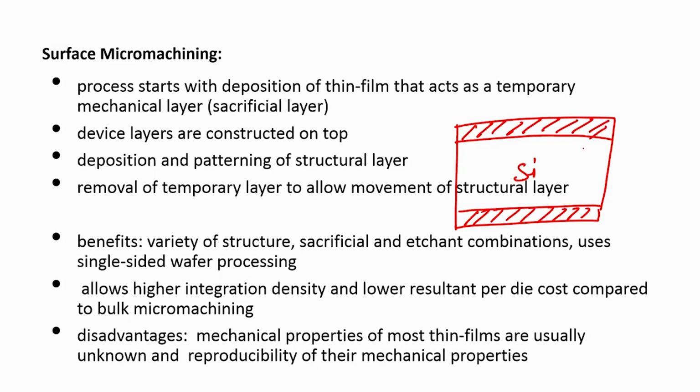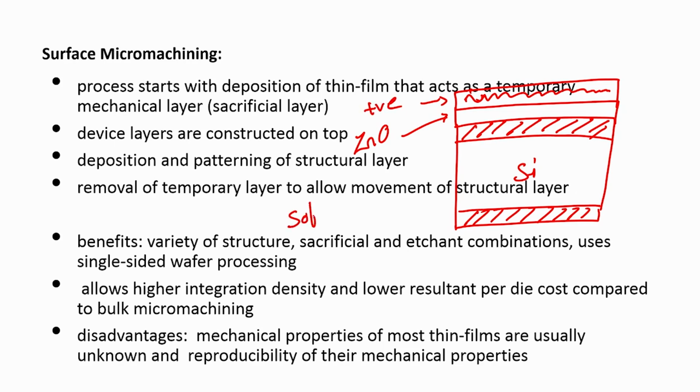And then what I am depositing is a material which is zinc oxide, and I am patterning it using photolithography, right. That means I am depositing zinc oxide, then the next step is photoresist spin coating. Let us say this one is my photoresist, spin coating photoresist. Next step is soft bake, 90 degrees, 1 minute, hot plate.